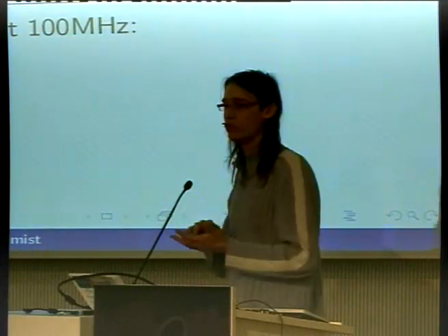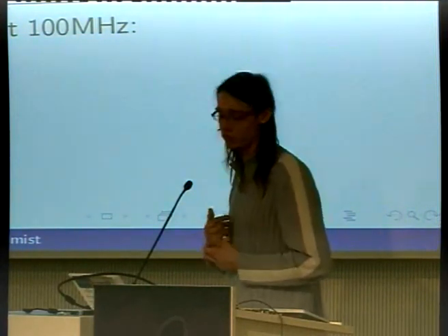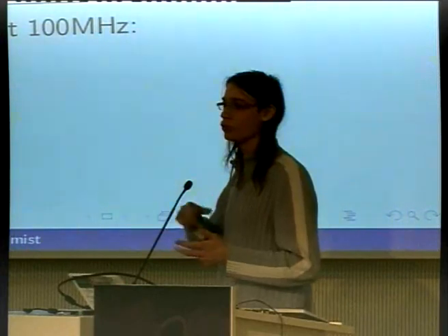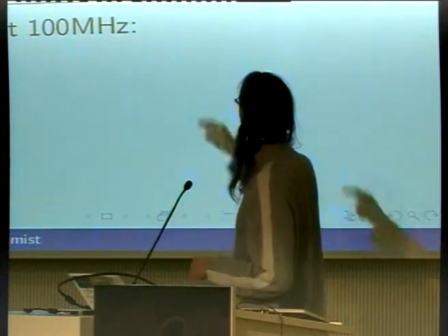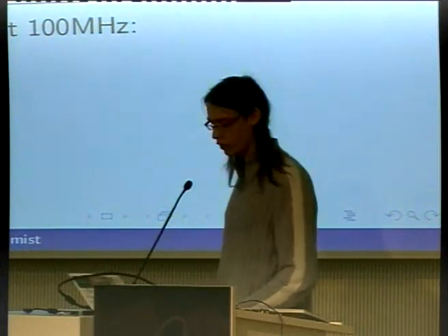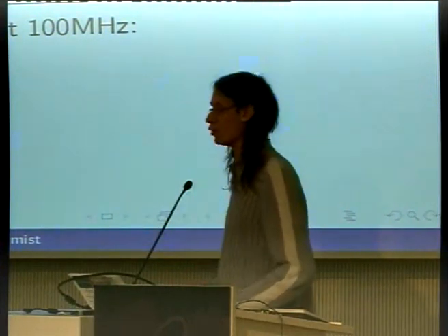So between the FPGA or the custom chip, if you want to make one, you will have a continuous flow of data, which amounts to 2.2 gigabits per second, and the total capacity of the memory is approximately 22 megabytes. That's only the basic system that you will need. So let's see what the memory market has to offer.